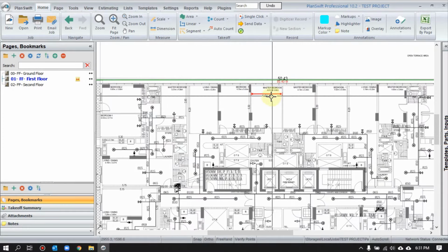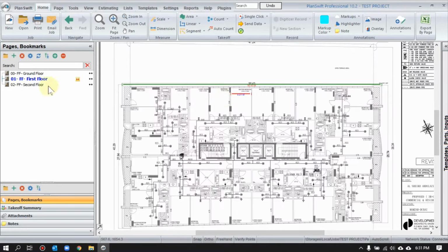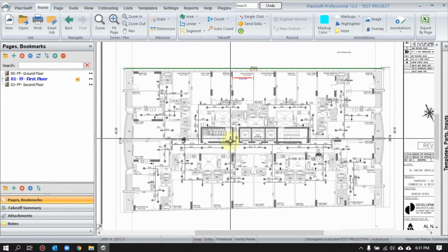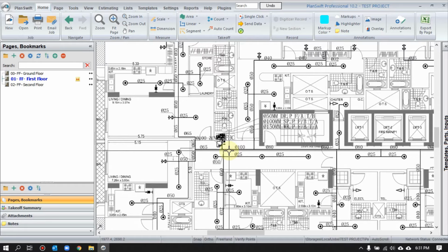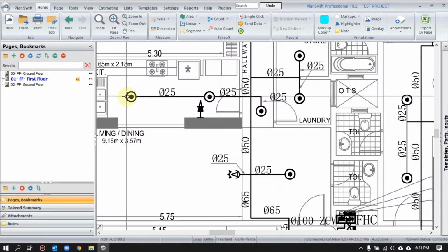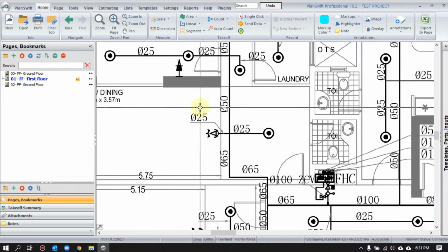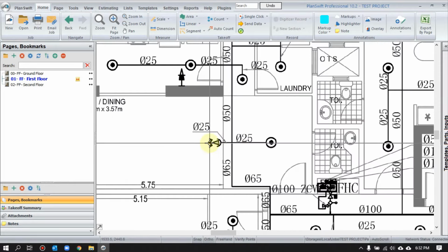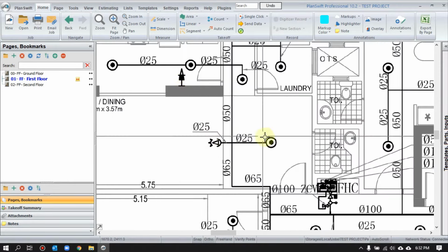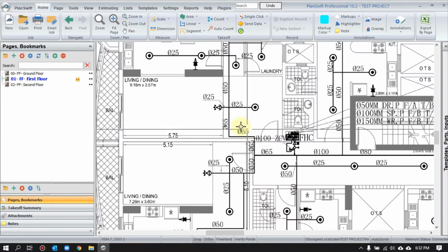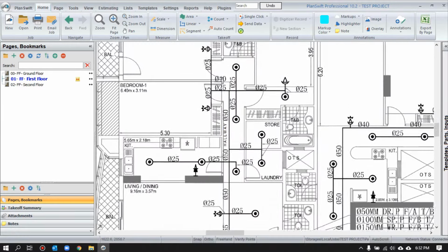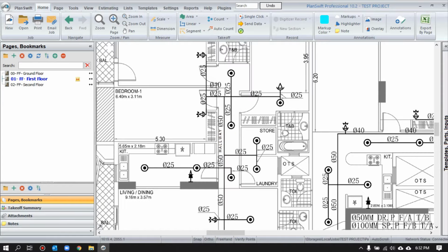Okay. So what we did till now, we added the files here. We set the scale. Now third, we need to measure something. So this is a firefighting drawing, as this is our focus today. In a firefighting drawing, our concern is to measure a few pipe sizes, and a few items including sidewall, extended sidewall, fire extinguisher, pendant, all these items. If you have a BOQ sheet, the software can give you a benefit here. Let me show you what that benefit is.